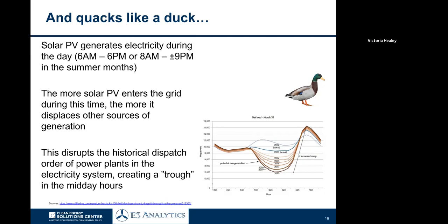The challenge here is actually that the more baseload supply, in other words, inflexible baseload supply you have, the more problematic daytime solar power generation becomes, because as soon as you start to have more solar, you more rapidly bump into this inflexible baseload. So you have a problem. Either the baseload supply needs to be made flexible, and there are efforts to try to do that, even to make nuclear plants flexible, old coal plants flexible. It's costly, and it's also not easy.